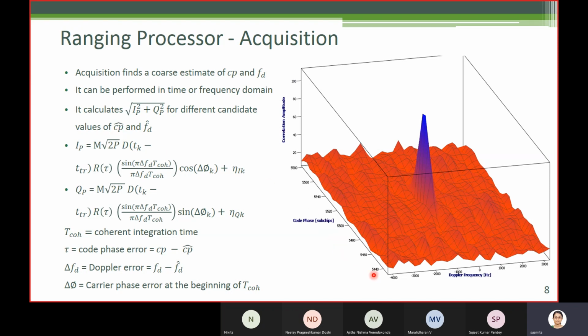So most probably in this case, the receiver used a 0.1 chip step size, and while plotting it zoomed into the portion near the peak. Those many points are considered, their code phases were taken, so you get the number of points along this direction.